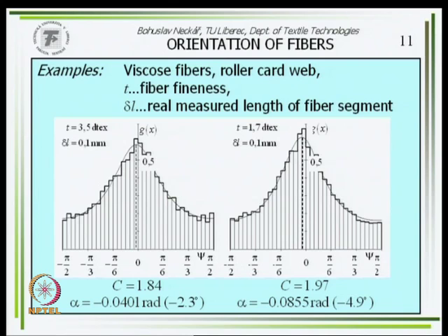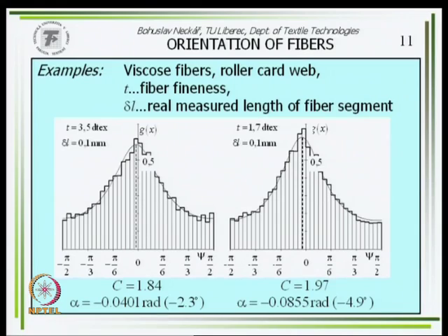We analyzed, using the tracer fiber technique, maybe a known experimental method to you, the curves of fibers in a fiber web. It was research for non-woven textiles, and we take a lot of points from this fiber to the computer. Then we reconstruct the whole curve of the fiber in the computer. Then we divide our fiber into very small, very short parts. In this picture, it was 0.1 millimeter.